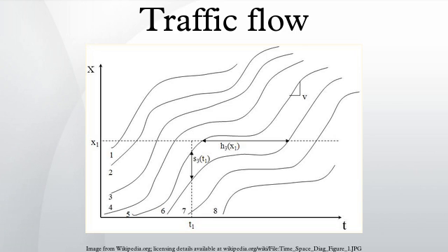The total of Area 1 and 3 represents the benefits of providing an alternative route. The total of Area 4 and Area 2 shows the total delay cost in the system, in which Area 4 is the total delay occurring on the highway and Area 2 is the extra delay from shifting traffic to city streets.